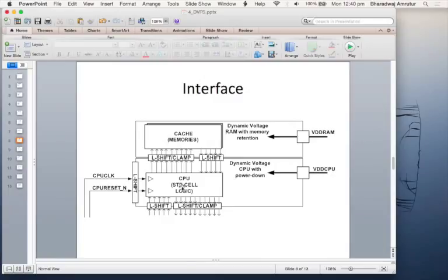Maybe to cut it down, you might have an intermediate power down state where you might have storage right there which is powered by a different supply, where you transfer the internal storage to that, and the internal one is powered down, but the other retains power, and then you can restore it back very quickly.